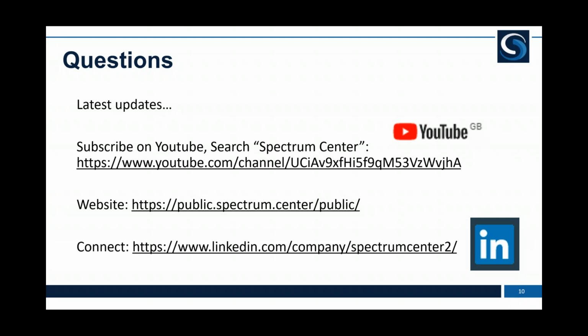What format must vector data be in for importing? So that's the import of vector data. What format does it need to be in? Yep. So for importing the vector data, we can import as either a shapefile or a KML file. So through the vector import toolbar, the projection has got to be WGS84, and certainly there's more details within the user guide of how to import and the steps to take to import a vector layer as well. So hopefully that covers off that question for you.